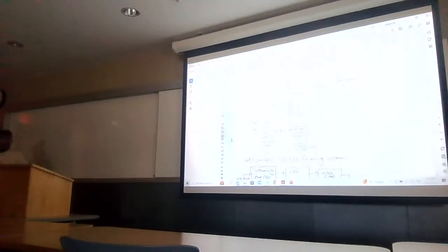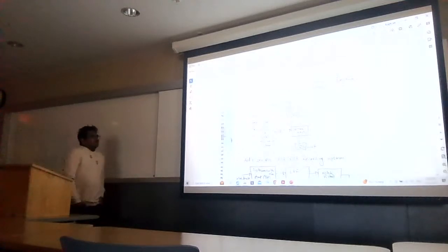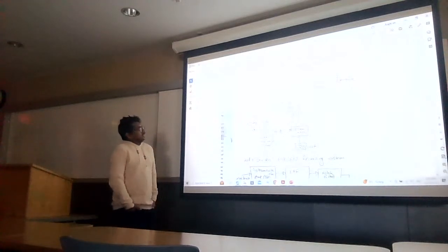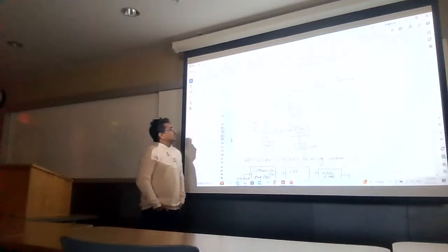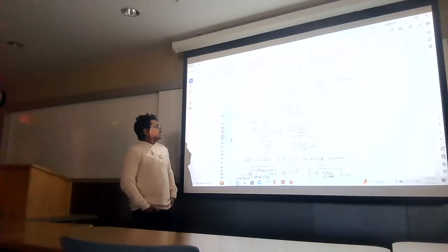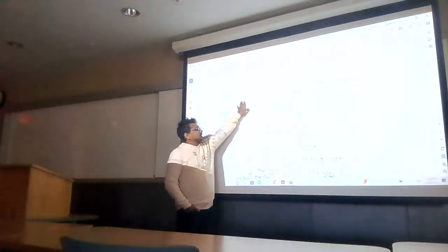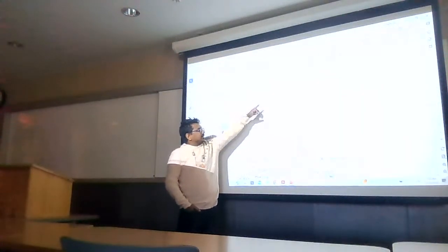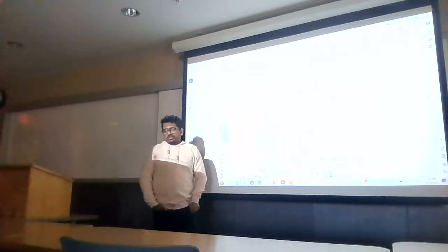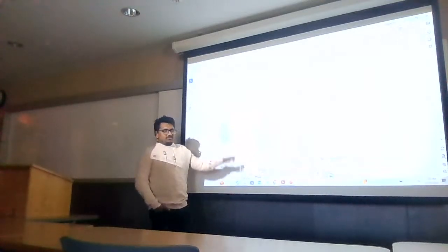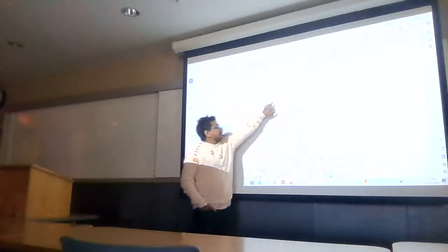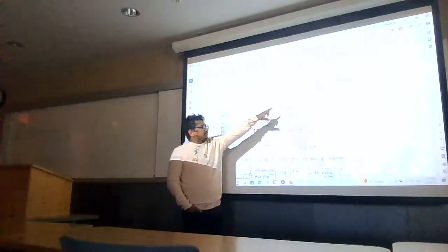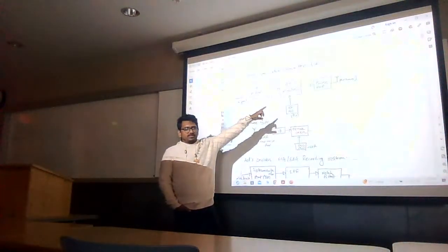Okay, then let's consider some typical block diagram of an analog system. If you consider any communication system, let's say this is the audio signal. If we take an example, there's a preamplifier, and after that there's AM modulation. I think you've studied this topic in several basic courses. And then there are also some reference oscillators, and after that there is some power amplifier, and this sends using the antenna.